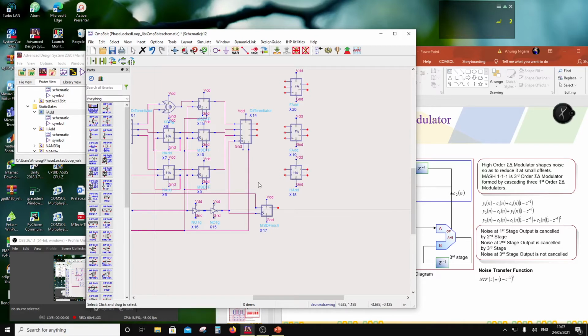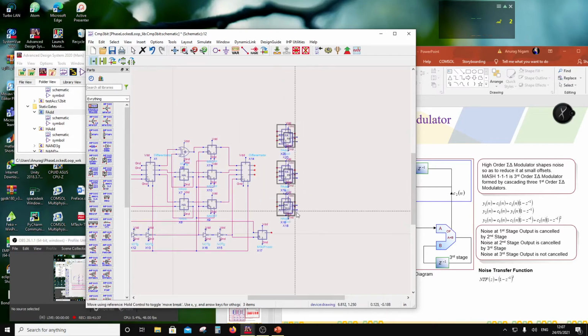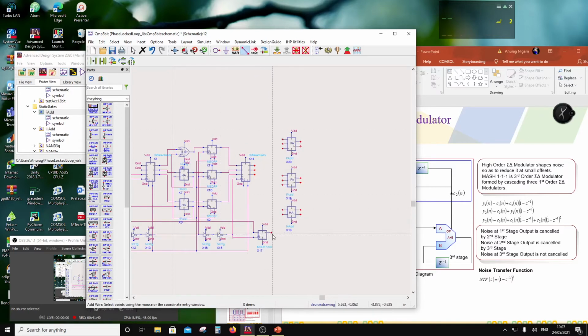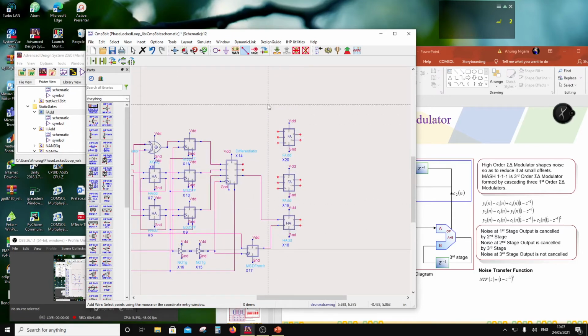Okay, to this half adder, I'm going to receive the input of this D latch, right? So that's a delayed copy. So I'm going to receive the input of this D latch. And then I will have the other input coming from the difference circuit, D0, right? And then this carry out would go in as a carry in. Okay, and to this full adder, the input is again going to be this D0 bit, which is delayed copy, and this one.